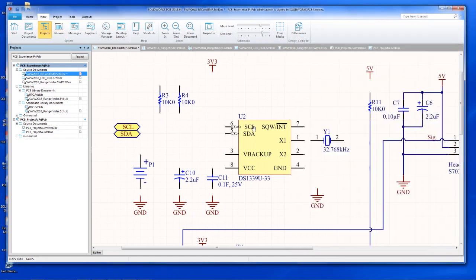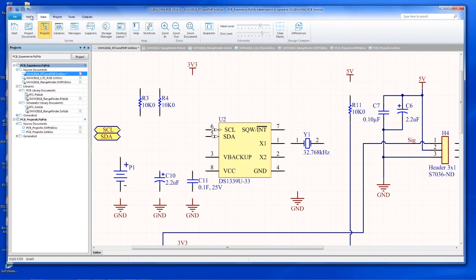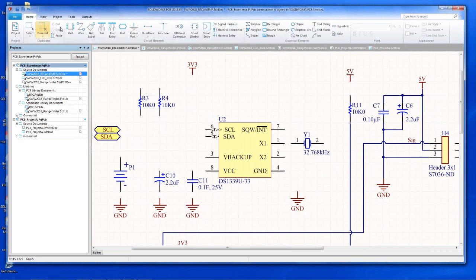Now we need to wire up our schematic. Again, wiring is extremely easy. I can go to the Home tab, where most of the commonly used commands are going to be found. Wire, place net label, power ports. If I need to add power ports, I have all these available to me. You can do harnessing, hierarchical blocks, multi-channel. A lot of functionality in this schematic tool. Like I mentioned, it's a complete standalone circuit board creation tool unto itself. But the value is the collaboration with SolidWorks.